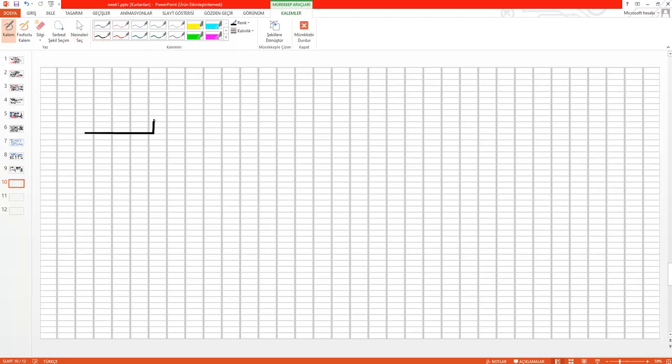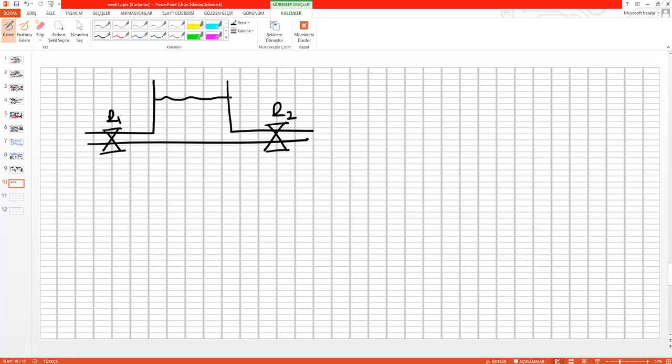If we have any hydraulic system like this one, we have a resistance value or valve value in here, R1 and R2, and we have some mass to be stored in here. How can I give P in and this to 0? How can I draw the electrical analog circuit based on this information?